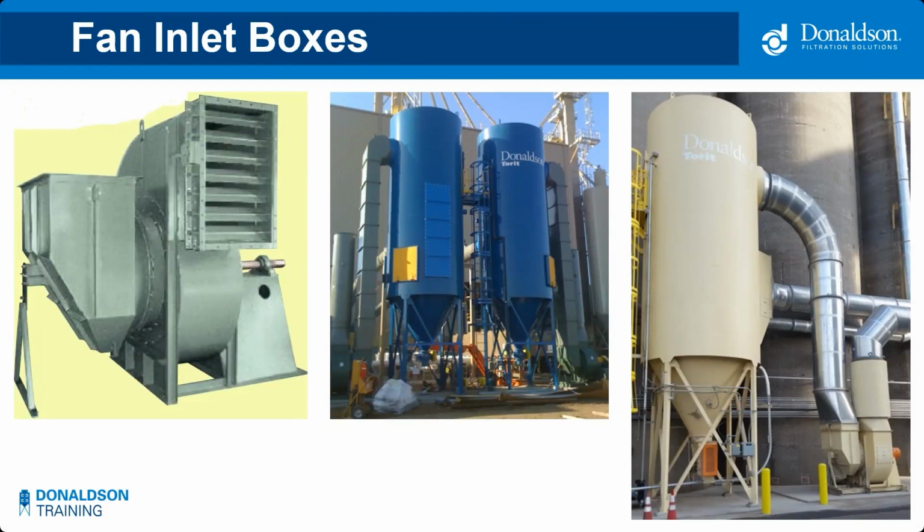The two pictures on the right are examples of the Donaldson RF dust collector. And you can see using that inlet box how tight the fan can be installed next to the dust collector. Again, real estate is expensive, and anything we can do to make the dust collection system more compact helps. These inlet boxes are extremely handy for this situation.